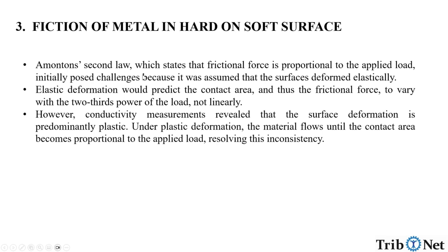Further, Amontons' second law, which states that the frictional force is proportional to the applied load, initially posed challenges because it was assumed that the surfaces deformed elastically. Elastic deformation would predict the contact area and thus the frictional force to vary with the 2/3 power of the load, not linearly. However, conductivity measurements revealed that the surface deformation is predominantly plastic. Under plastic deformation, the material flows until the contact area becomes proportional to the applied load, resolving this inconsistency.